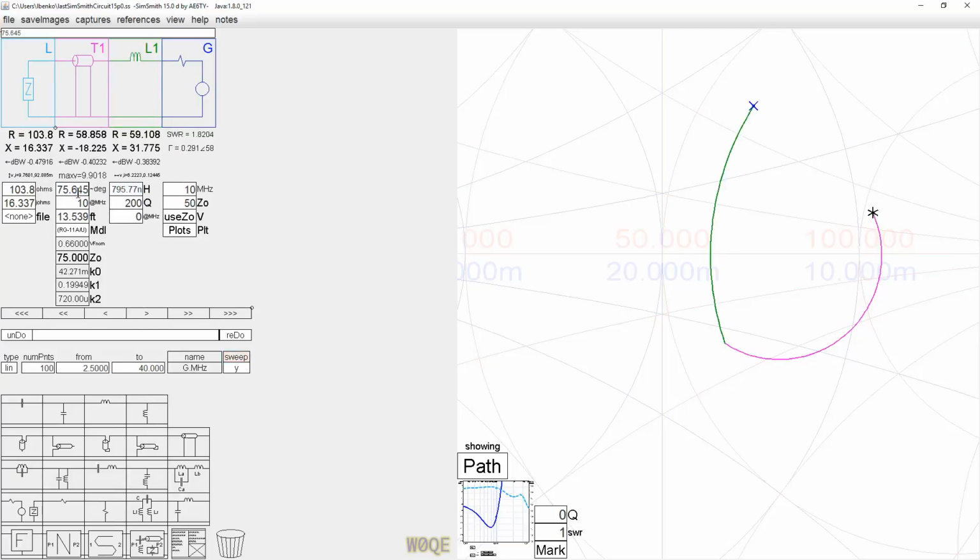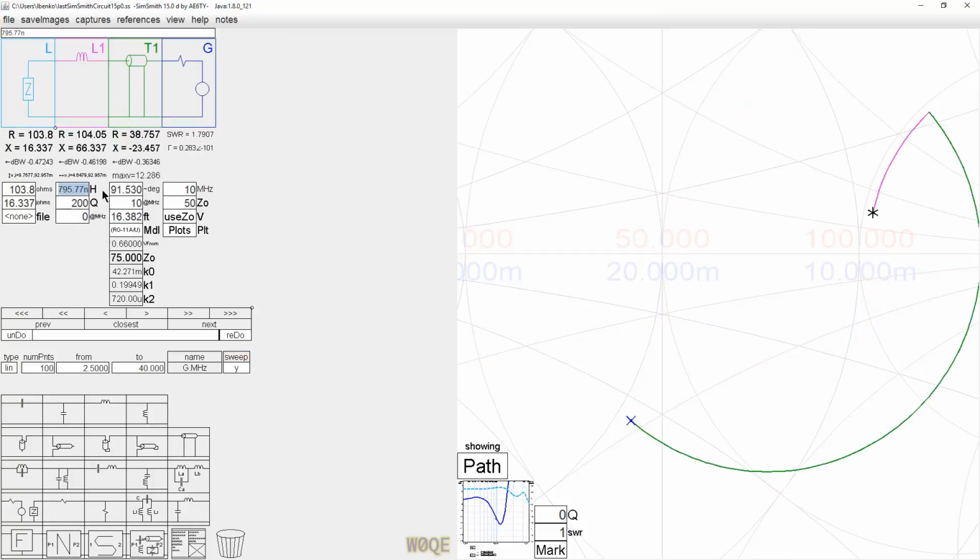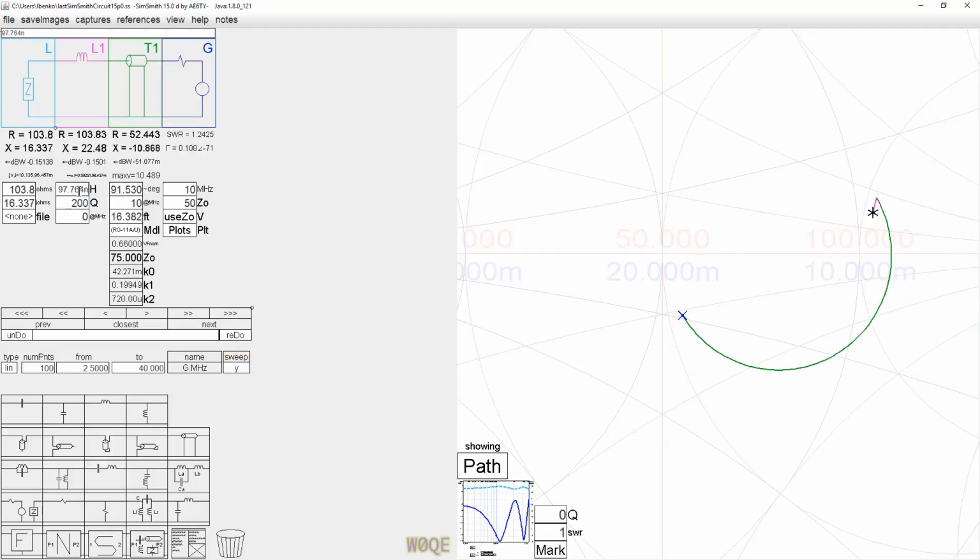No, that's not going to be working that side. Let's put a series inductor here and see how that works. That's going to work just fine. Okay, in this case, 129 nanohenries in series with our transmission line. Now it's 107 degrees instead of 68 degrees. Again, much better match than just using a 90-degree section. There are so many ways you can match this that are better than just putting a 90-degree piece of transmission line in. I'll do one more example here.